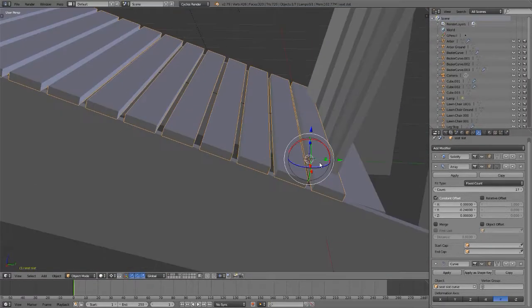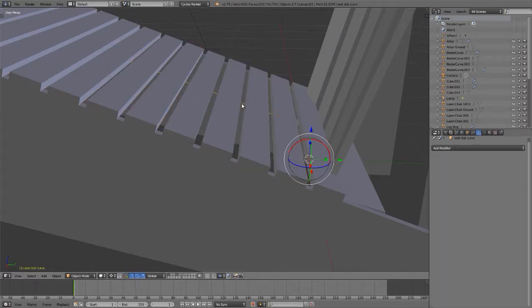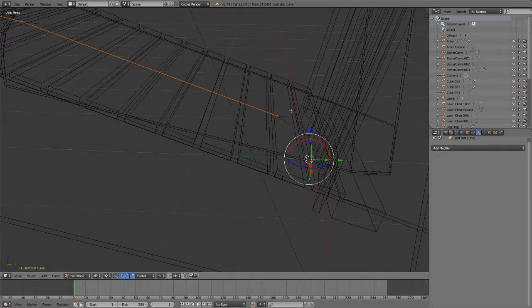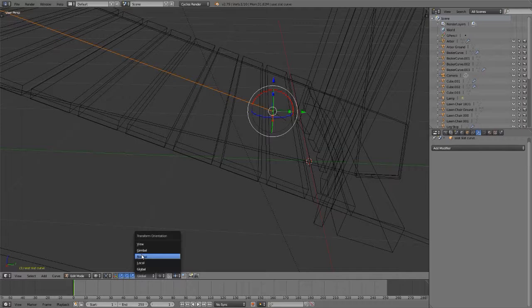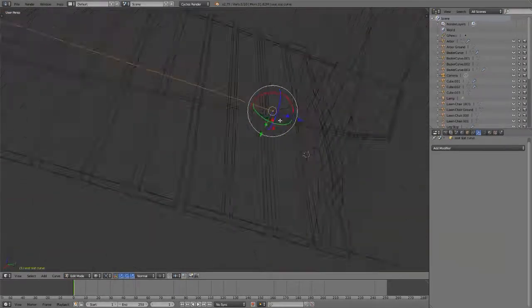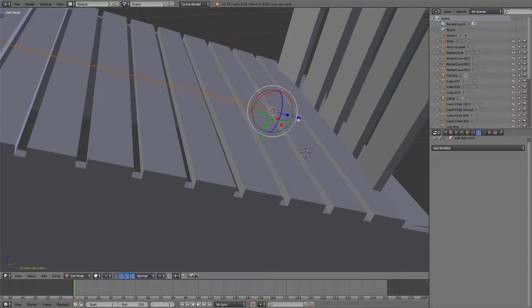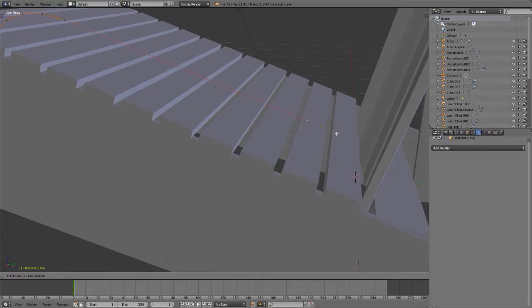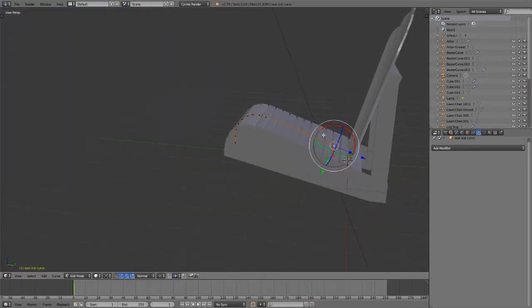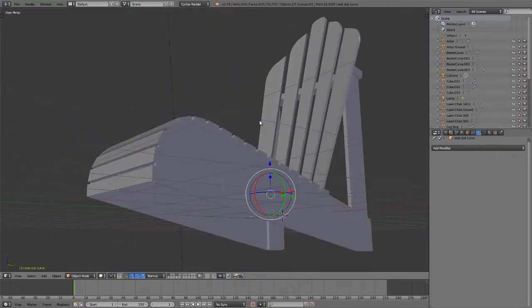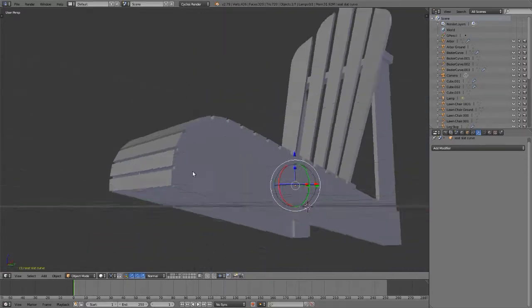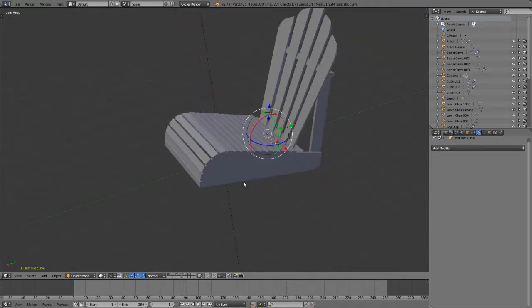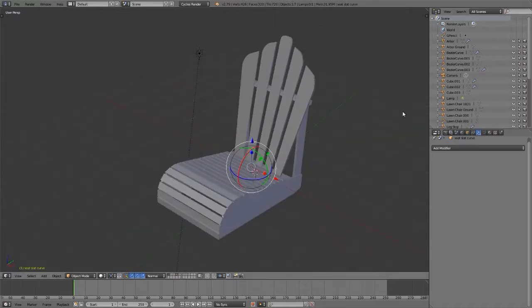So now let me select the curve and go into Tab Edit Mode. Select what is a control point, and see if I can move it along its own normal. That's good. Let's do it. It is now off the other slats and begins more accurately where I wanted it. Tab into object mode, and look at this, it nearly bottoms out in the correct spot. Sweet! Good for you! Control S, save your change, so when the cat steps on the power cord, you don't have to kill it. The computer, that is.